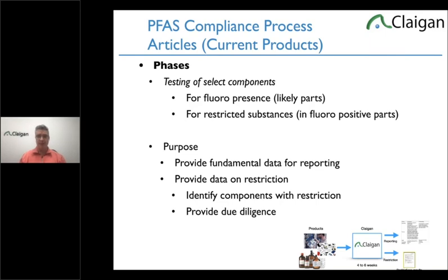And then those are the parts I mentioned earlier. The restricted materials don't have to be in them, but they can, and the only place they are, the restricted ones, are in the reportable PFASs. So we find the PFASs, whether it's obvious or we pick it up as a fluorine measurement, and those are the parts we check for PFOA and family. We can't test all of them, but there's no expectation to test all of them. This gives you what components to change at one level, or justifies you don't have it, or justifies you don't have it except for this situation, which you correct. And that proves that you've done the work.